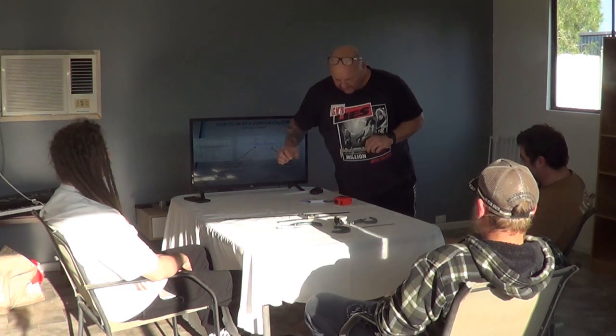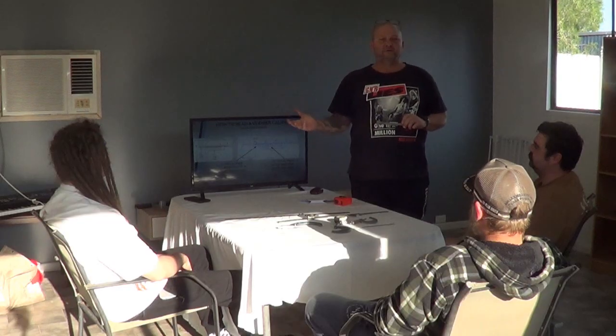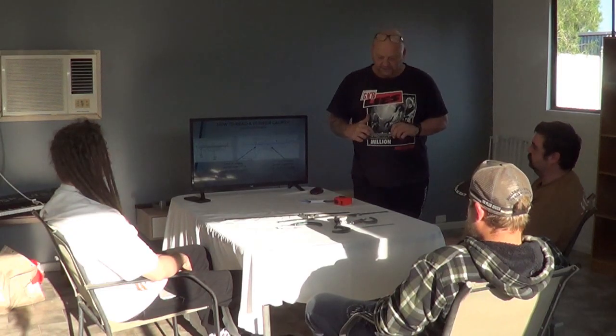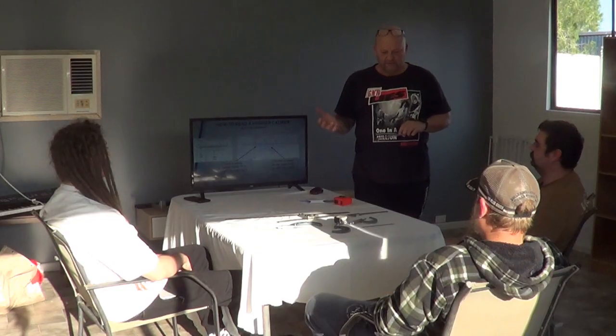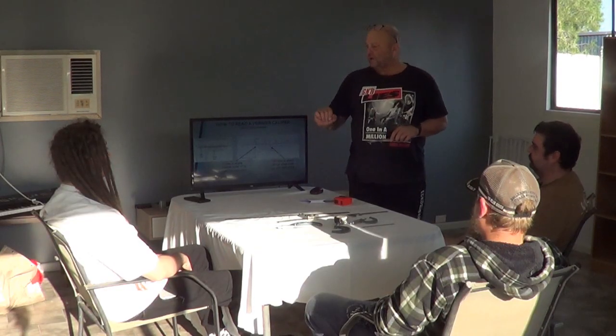You've got what's called the main scale at the bottom, where each small division is the same as a tape measure, a millimeter. Every 10 millimeters is a centimeter. However, you've now got a third scale, your vernier scale, which breaks it down into tenths of a millimeter.